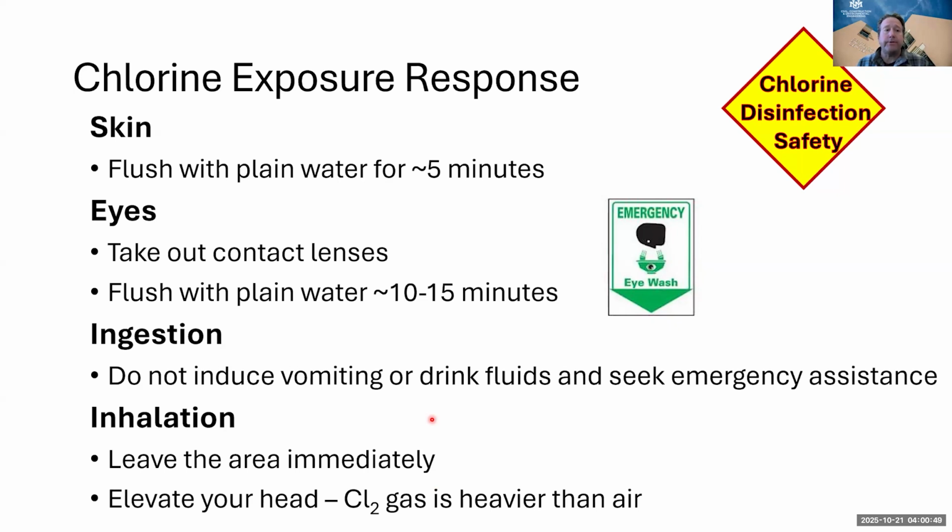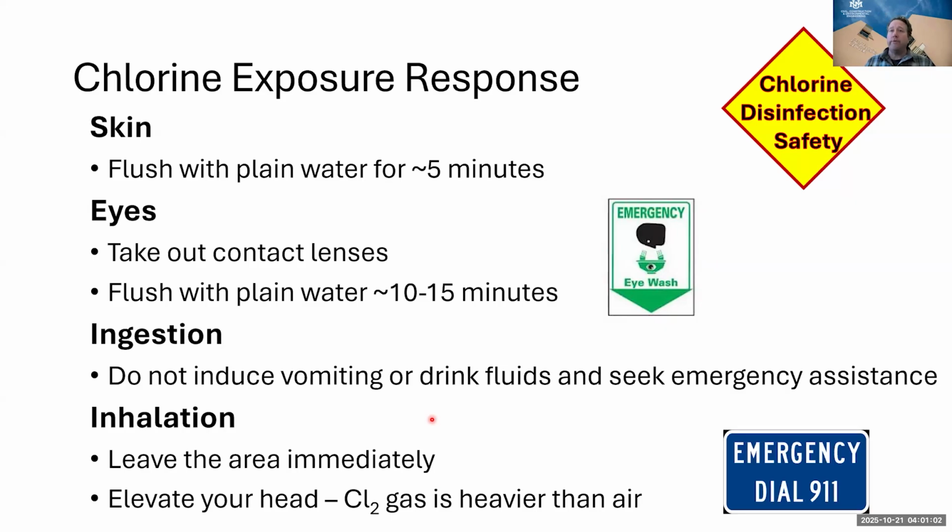Inhalation. So if there's a chlorine gas leak, leave the area immediately and then elevate your head above as high as you can because chlorine gas is heavier than air. And then, really, for ingestion, for inhalation, you really need to seek emergency assistance to address that.